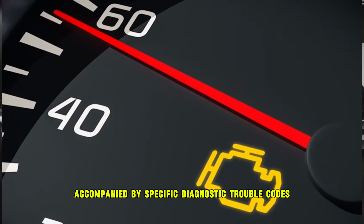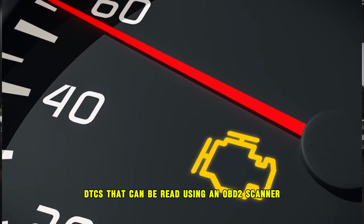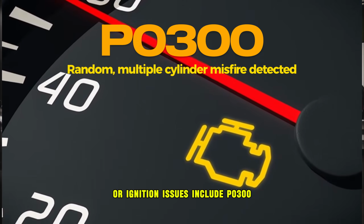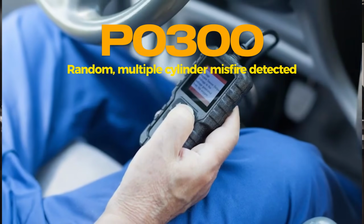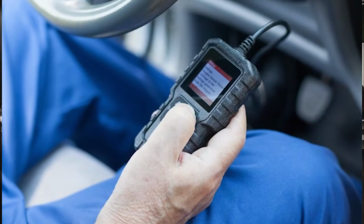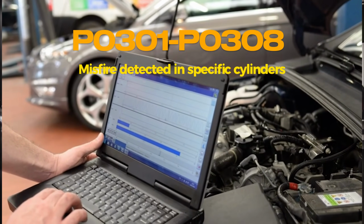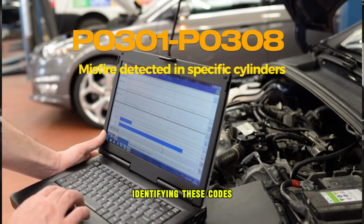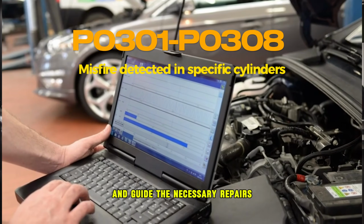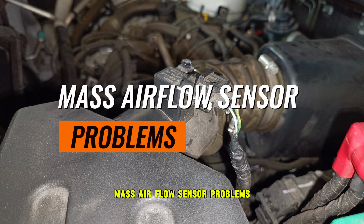When the check engine light comes on due to spark plug or wire issues, it is typically accompanied by specific diagnostic trouble codes, DTCs, that can be read using an OBD2 scanner. Common codes related to spark plug or ignition issues include P0300, random, multiple cylinder misfire detected, and P0301 to P0308, misfire detected in specific cylinders. Identifying these codes can help pinpoint the exact cause of the problem and guide the necessary repairs.